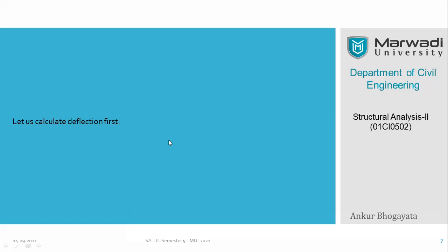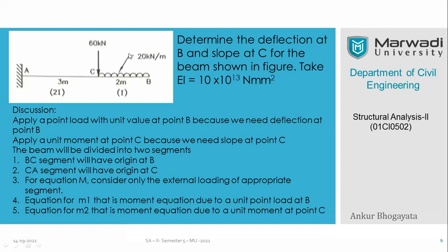So here again, if I go back, you can see that 20 is the UDL. So X starts from point B. We are standing somewhere here, right? If I take some pen here, we are standing here, and the X is to be considered from this origin, right? So this is the length. Now we have X, and this is a load already with us. So 20X is the total load, and that will be acting at half, somewhere here.